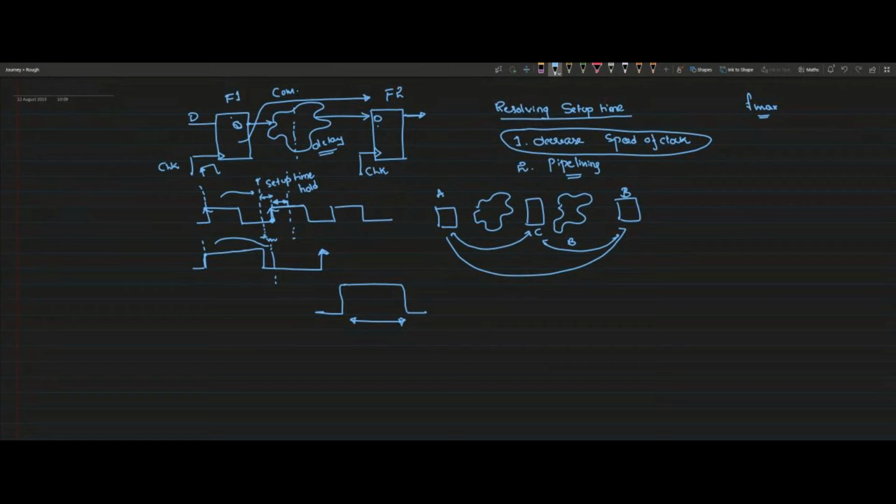Usually if it is synchronous, meaning the data is clocked, then hold violation is a rare case in FPGA-based designs, because FPGA is designed in such a way that you will not get a hold violation. But there will be some exceptions, due to the logic you design, such as CDC paths, where you will see hold violation. Basically, you have to make sure that the data width is sufficient so that you can capture properly at the receiving edge.